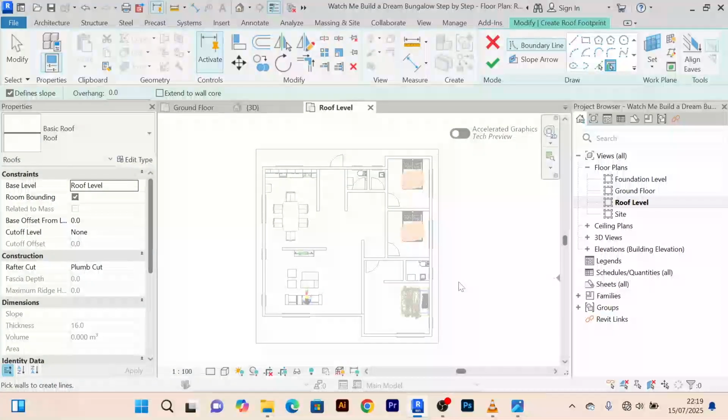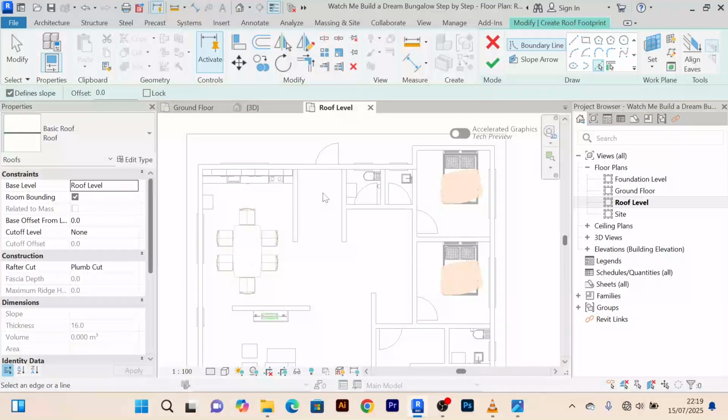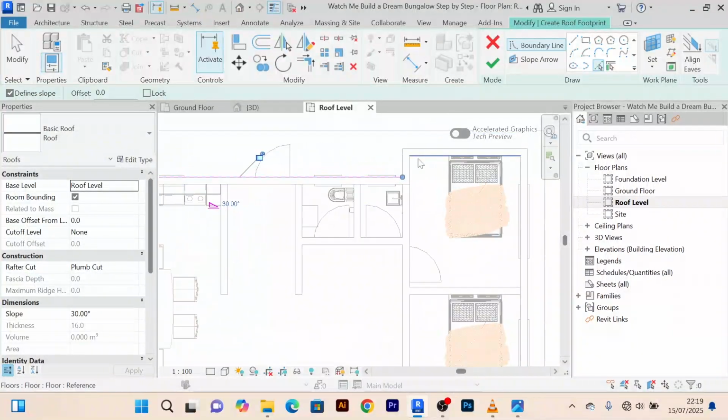The same way we use the pick lines is the same way we're going to also pick lines for roof. Now when I click on my pick lines here, I can now start selecting roof. If you are creating a hipped roof, which we are going to start with, you can pick the exterior sides.